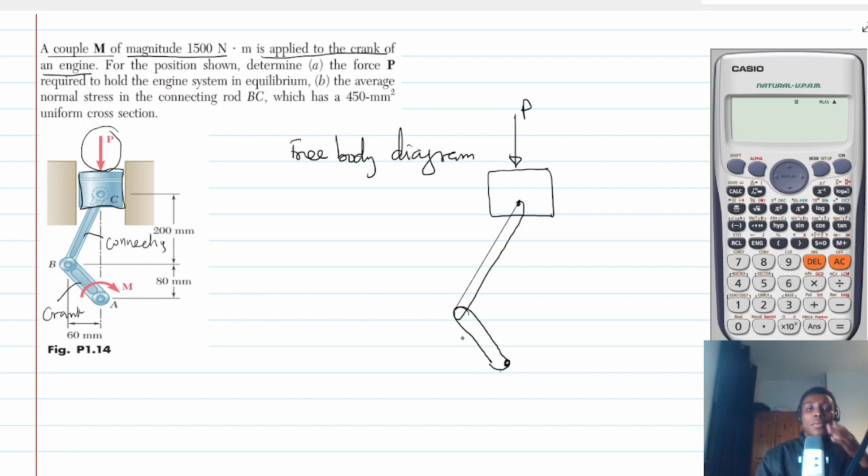Okay. Now this connection here at A is some sort of a pin, because if there is no pin here, then it means A can also move just anyhow. But then there is a pivot so that this AB will rotate about A. So A can be thought of as a pin with reaction Ax and then Ay.